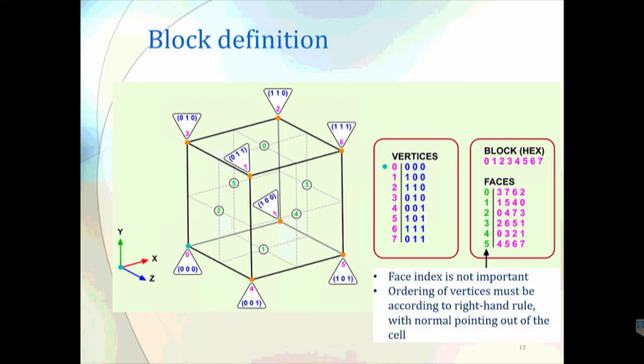So when we are defining the planes for our block, we will not take the bottom plane and the top plane because they are not xy planes, they are xz planes. Which is the xy plane? This rear plane and this front plane. So we are going to define our block using the rear plane and then the front plane. How do we know which is the rear plane and which is the front plane? The plane in the positive z direction is the front plane. The plane at the back, at the start of the coordinate system, is the rear plane.